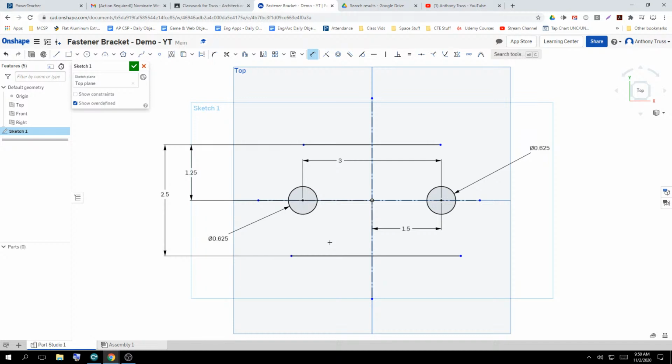I could see some people right now early on, the big curved outside parts of the drawing or the model where it says radius 3/4. If you were to double 3/4, or if you had 75 cents in one pocket and 75 cents in the other pocket, you have $1.50 in total, right? So this outward arc, where my mouse is going back and forth, that's annotated as radius because it's not a full circle. If it was a full circle, it would either say drill or diameter.